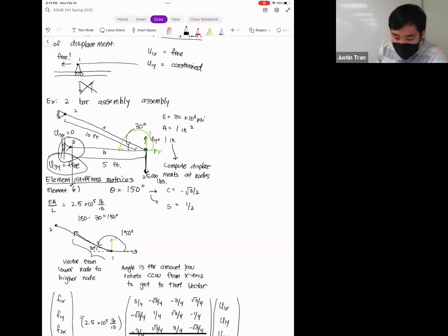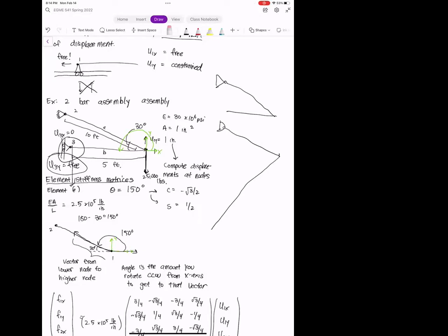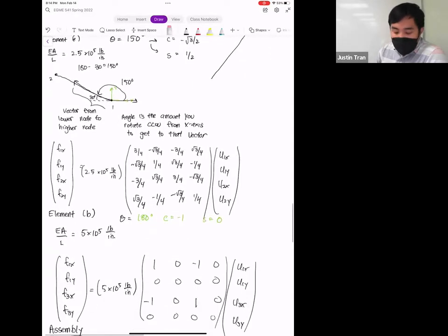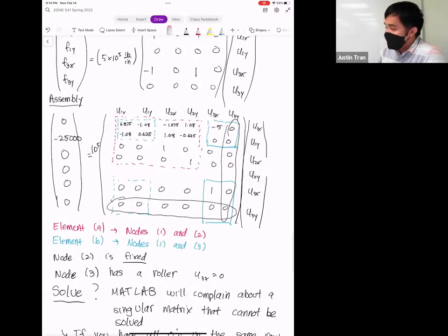And so if you want to play it out, it's going to start something like this, and then the displacements are going to get extreme. As soon as you start pulling down, or even before that, just through gravity, this bar is going to start rotating like that. It's going to keep rotating until it reaches its physical limit, and the displacements are too large for it to handle. So the only way to solve this problem, when you get a situation with all zeros in a row and column, is to artificially increase the amount of constraints.